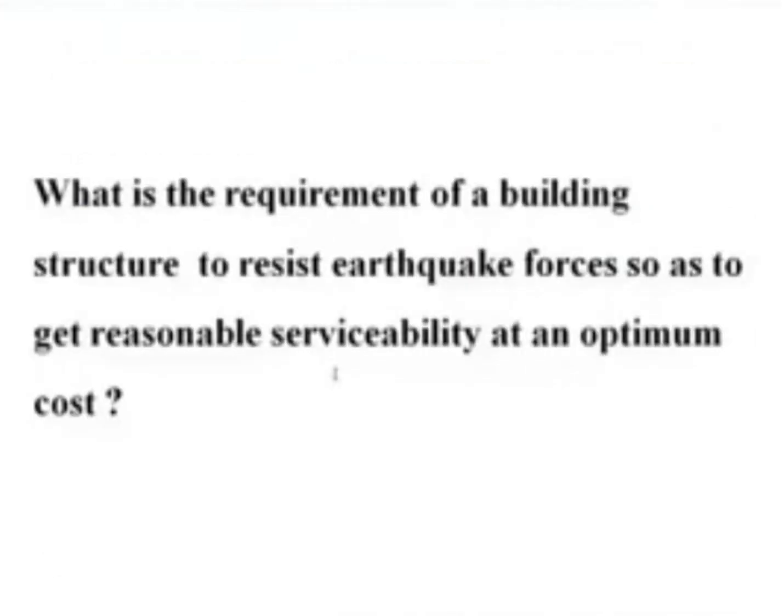Now, what is the requirement of a building structure to resist earthquake forces so as to get reasonable serviceability? Try to understand. I am giving importance to reasonable serviceability at an optimum cost. That means, if you think that earthquake will take place and there will be no damage, absolutely it will be perfect. It will behave like an elastic structure. No, in that case, the cost will be extremely high,